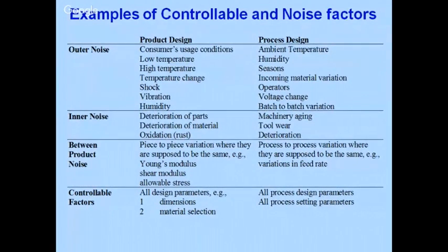Even if I take another example from the mechanical engineering background, you are carrying out a machining operation, maybe a turning operation with the help of a tool. Now, as the process is being carried out, the tool is wearing, isn't it? The quality of the tool, maybe the sharpness or angle, nose radius, whatever we may call it, at the beginning of the cut is not the same as at the end of the cut.